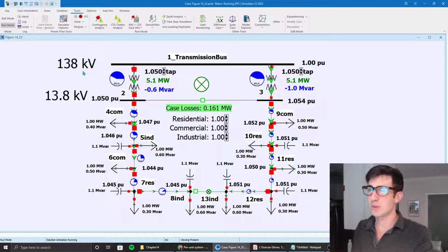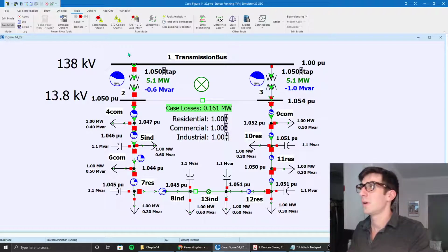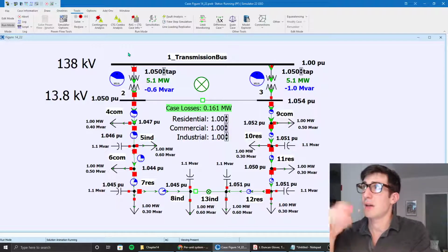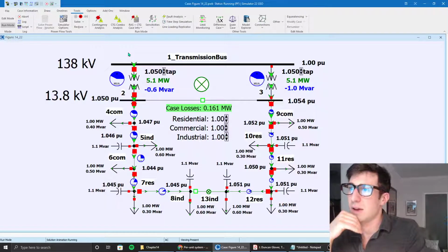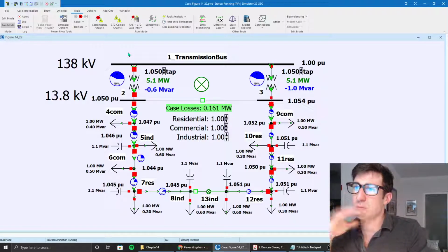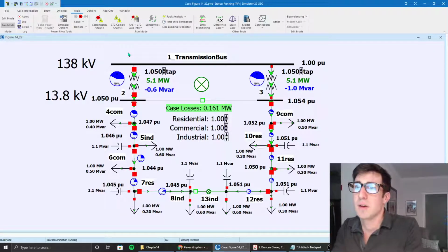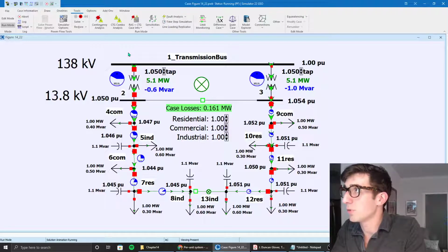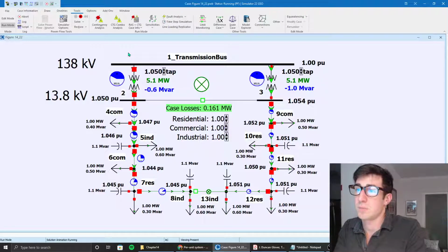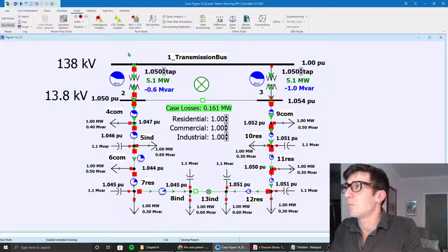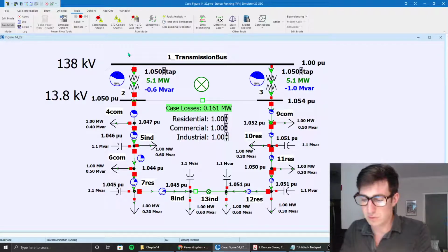So if that was too confusing, basically what you're looking for when you trace back up to high voltage is that everything will be 1 per unit base value. The per units will change, so you're dealing with easier numbers than say 138 kilovolts to 13.8 kilovolts to 120 volts. It makes the math a little bit more convoluted when you do stuff like that.